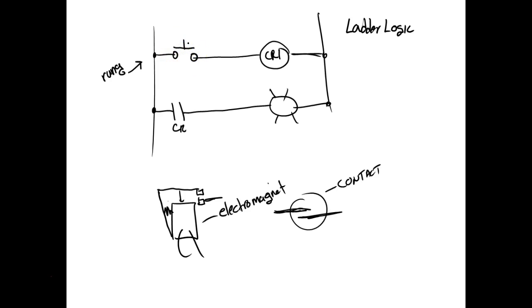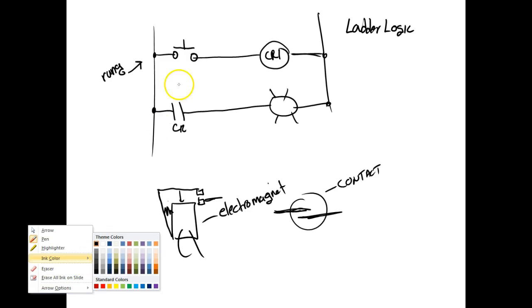So this is a symbol for a momentary contact push button. Y'all understand what that term means? Momentary contact means it's only made when I do what? Push it down. Well, then we've got this guy right here. So this would be a normally open, which means the circuit is not made until I press it.